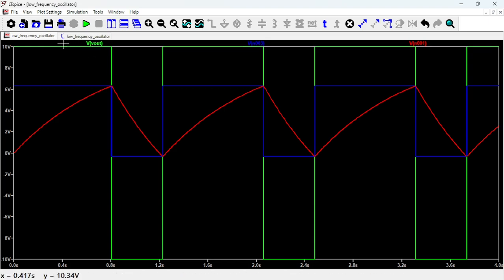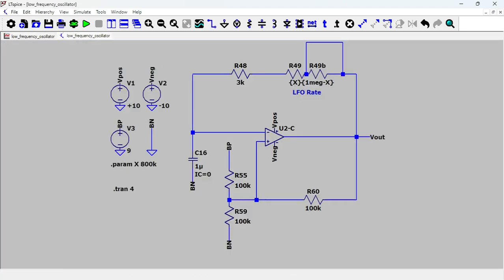And what happens to the other branch, the positive feedback? What happens to this voltage here? Again, you have 4.5 volts coming from the voltage divider, but now you have current going this way. This is 4.5, and this is minus 10, so you have current going this way. So here you don't see 4.5, you actually see 0.